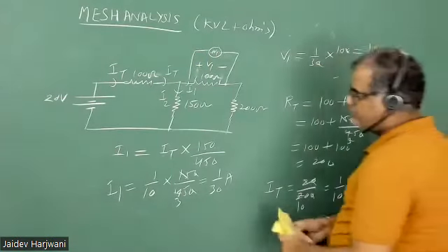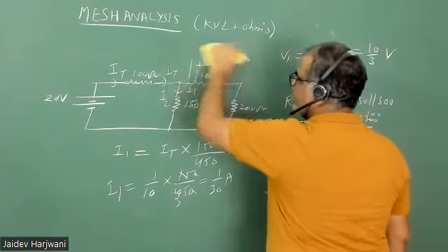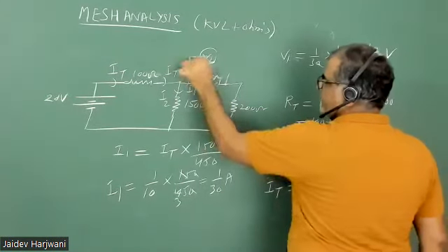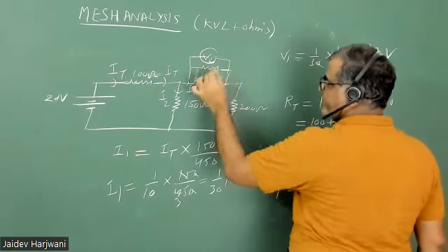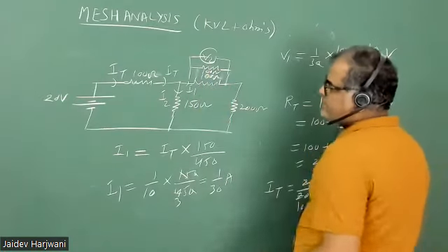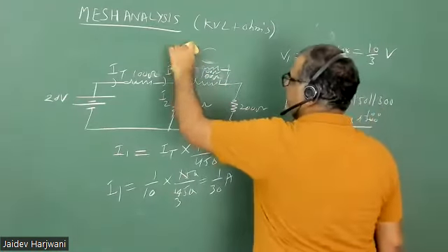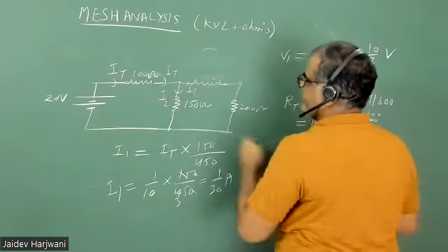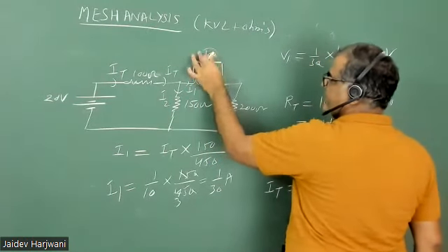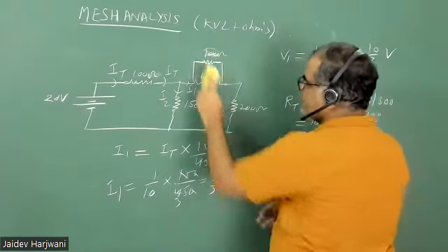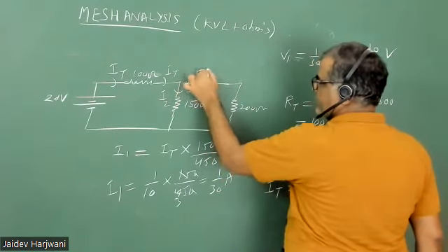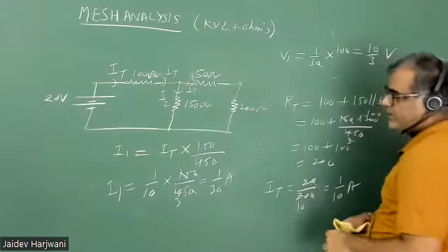Now let us do the second calculation. In the second case, you have a voltmeter V2, which has a resistance of 100 ohm. Now this resistance is comparable, so it will change the circuit resistance. If it is 100 ohm and the parallel is also 100 ohm? 50, sir. So effective is 50. So now this resistance has changed, you have resistance now 50 ohm. Again, do the calculations.